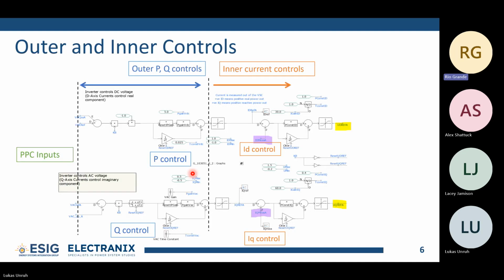If you don't extract that power out of the DC bus, the voltage is going to rise very quickly. So in the control space, we can just control that DC voltage to some reference, and that's the control mechanism for taking power from the turbine side out into the grid through the DC side. It's a similar thing for PV as well.